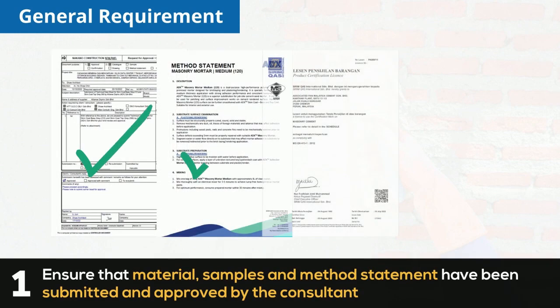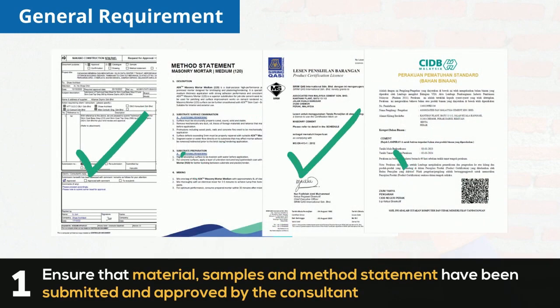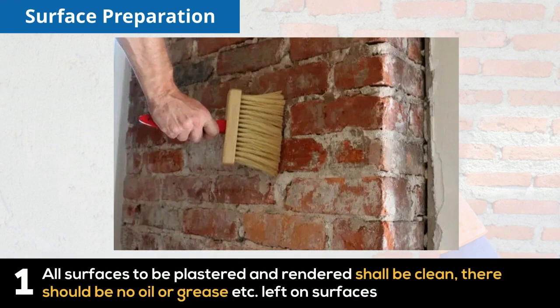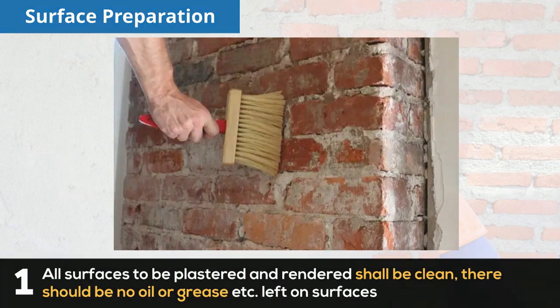General requirement: ensure that material, samples and method statement have been submitted and approved by the consultant. Surface preparation: all surfaces to be plastered and rendered shall be clean. There should be no oil or grease etc. left on surfaces.